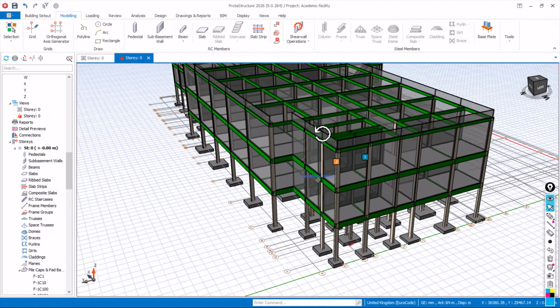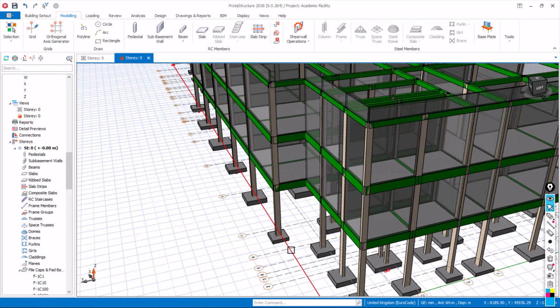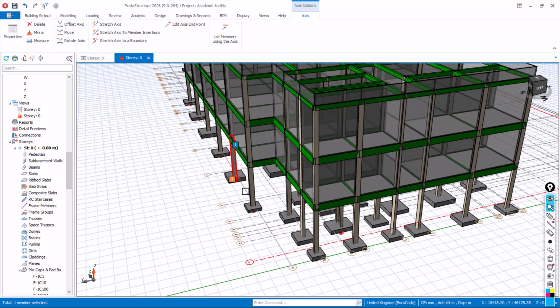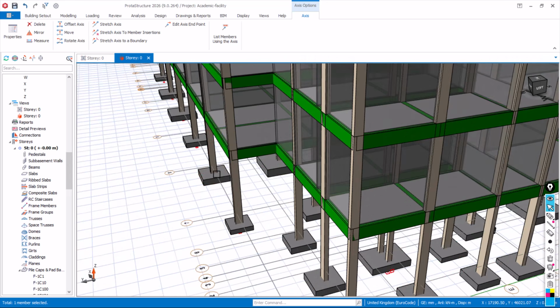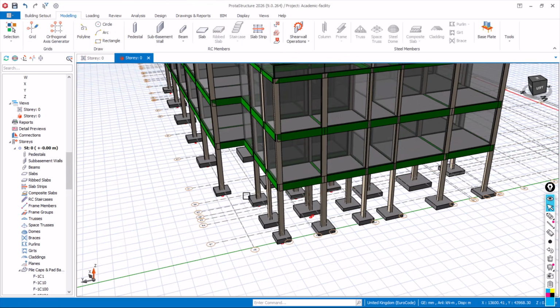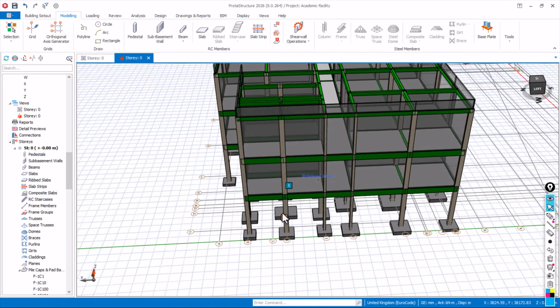During the setting out, we discovered that on grid line A and grid line 1, these footings were already encroaching into the other property boundary, which is not allowed based on construction. And then we advised the client to maybe shorten the width of his building. Understand, that is the only approach: shorten the width and the length.